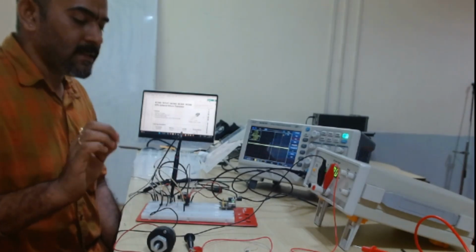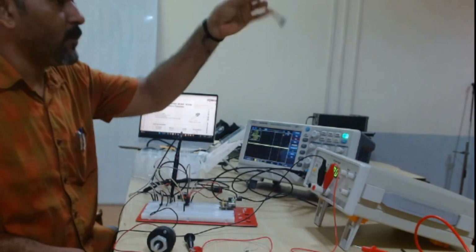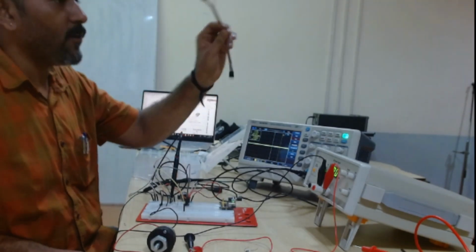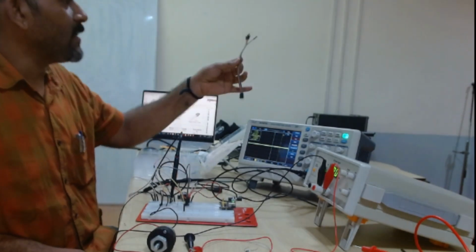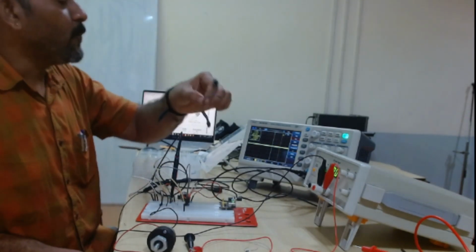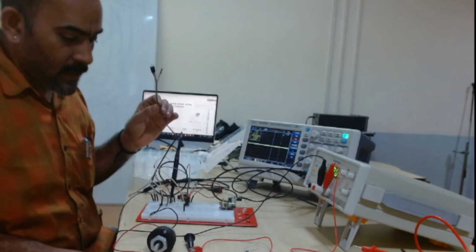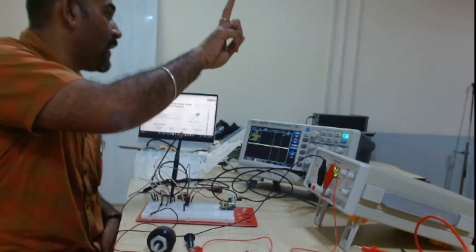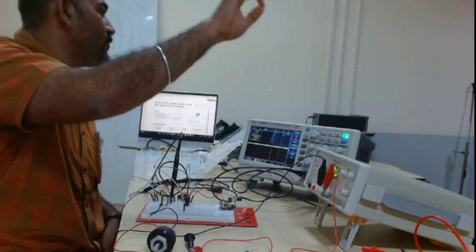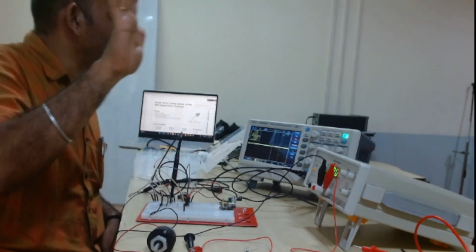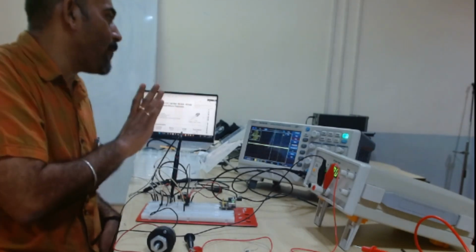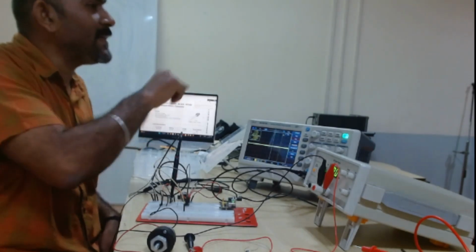Now, these wires are color coded, so that it is easy for you to track. If there is a color coded option, always go with it. You can easily track the wires. Normally, we will have at least 2 colors, black and red, and generally red is connected to supply, black is connected to reference. That is the general tendency. If you follow that, half of the problems are reduced because it becomes easy to track.